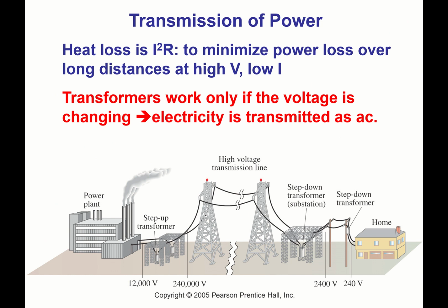Okay, so what do we use it for? Well, the primary reason that transformers were invented was to allow us to conduct electricity from a power plant that's a long way away from where our house is without losing a lot of power. So when power goes down the line, we lose energy at the rate of the current squared times the resistance, and we know the longer the wire, the higher the resistance.